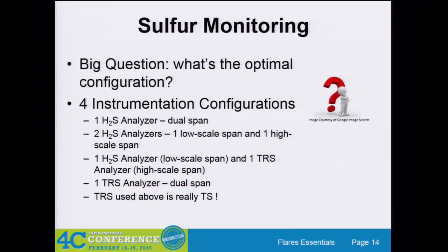Herman, I'll ask a question on that. With the exception of like PSVs for emergency relief, those can still be connected? No. The only things that can go to that flare header is what goes to the heater or boiler. Yes, because this is the TRS, the RCA threshold, which includes process upset gas. So if you have a PSV that's going to put process upset gas, it still needs to be monitored under this. But for this, the thing I was talking about here with the three options. So 500 pounds? Yes. Okay, so 500 pounds includes the upset gas, and that would be, okay, thanks. Yep.